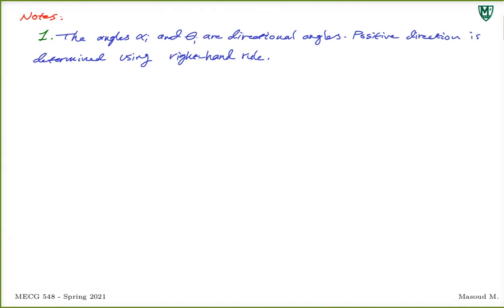Second thing you have to remember goes back to the configuration of joints, and we use that more frequently, especially when we are setting the orientation for the base frame. This one is talking about rest position or home configuration. This term, home configuration or rest position, is used to refer to a position for an arm where we can make as many axes parallel to each other as possible.